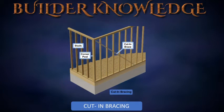Cut-in bracing. Cut-in bracing is usually made from 2 inch by 4 inch material. It is toe-nailed between studs and inserted in diagonal progression between studs at a diagonal from the top of a corner post to the sole plate.